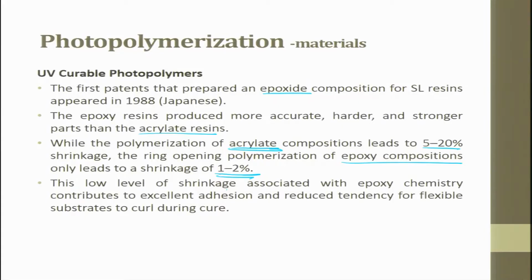This low level of shrinkage associated with epoxy chemistry contributes to excellent adhesion and reduced tendency for flexible substrates to curl during curing. So, this epoxy chemistry made a big change in photopolymerization, which is the principle used in the stereolithography process. So, from acrylate based we went to epoxy chemistry.